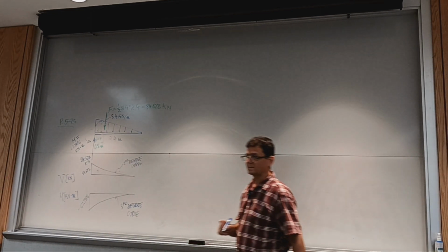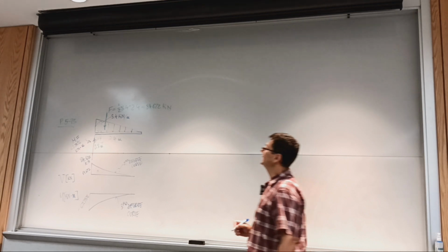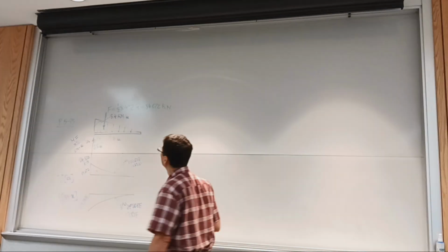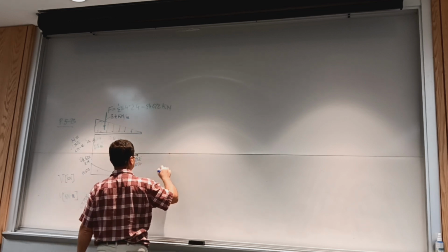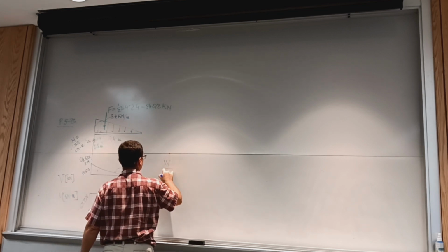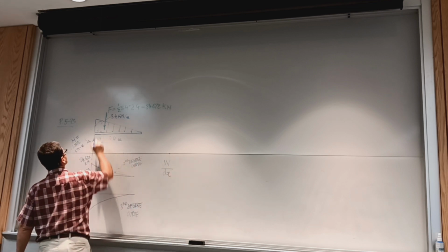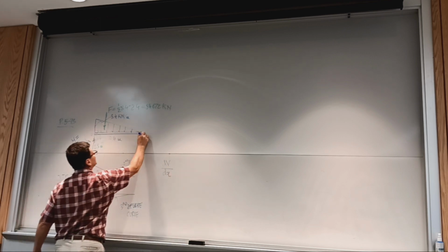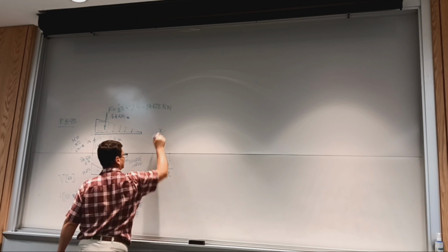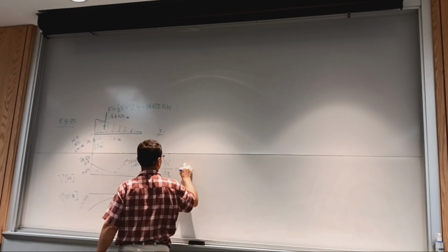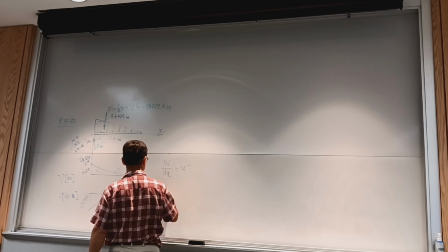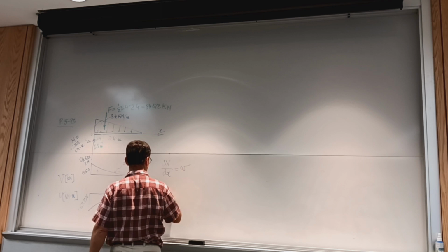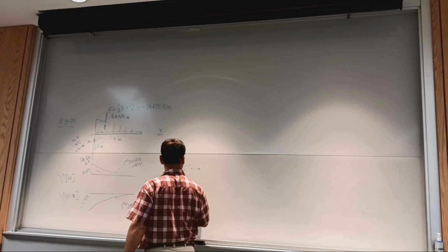Okay? Now, if we want to write equations of the two curves, we can do it via integration. So we have dV over dx, and x is measured from the origin here, positive to the right. dV over dx is w. And for moments, dM over dx is V. So I can move to integrating.